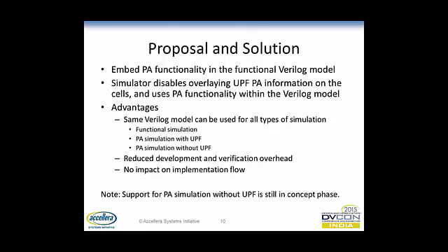The proposal is to embed the power functionality in the functional Verilog itself. By doing this, the simulator should disable the overlaying of power functionality from the Liberty onto the Verilog model if it finds that the power functionality is already present inside the Verilog model. By this approach, the same Verilog model can be used for all types of simulations, be it functional simulation or power simulation with UPF or without UPF.